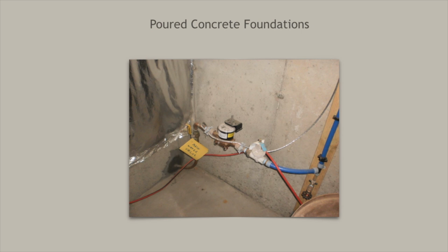Poured, in-place concrete foundations. The most common type of foundation today is the poured in-place concrete foundation. Once the forms are placed, it is simply a matter of pouring the concrete into the voids of the forms and allowing the foundation to set up for a minimum of 24 hours before the floor is installed.